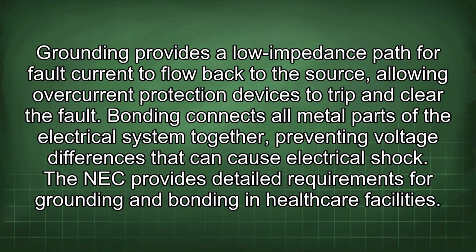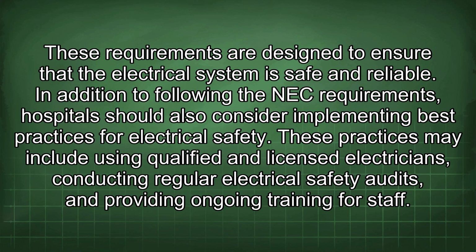Grounding provides a low-impedance path for fault current to flow back to the source, allowing overcurrent protection devices to trip and clear the fault. Bonding connects all metal parts of the electrical system together, preventing voltage differences that can cause electrical shock. The NEC provides detailed requirements for grounding and bonding in healthcare facilities. These requirements are designed to ensure that the electrical system is safe and reliable.